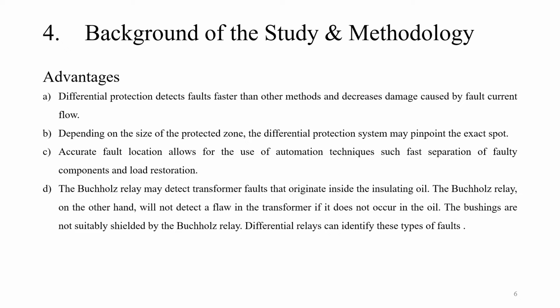The Buchholz relay may detect transformer faults that originated inside the insulating oil. The differential relay, on the other hand, will detect a fault in the transformer even if it does not occur in the oil.